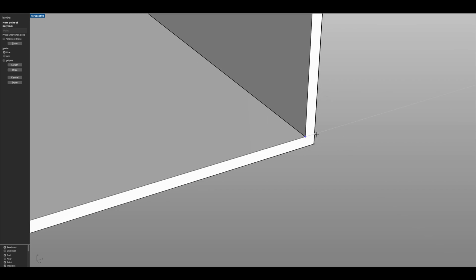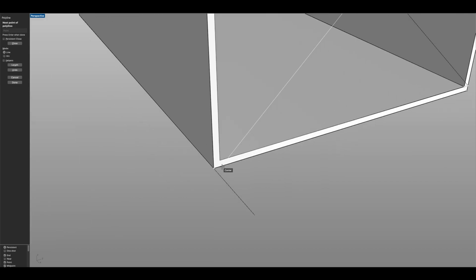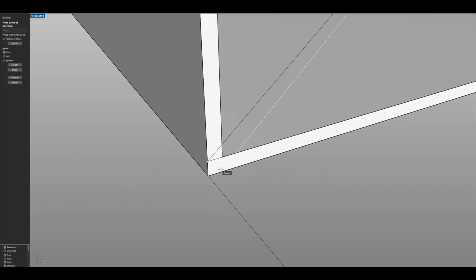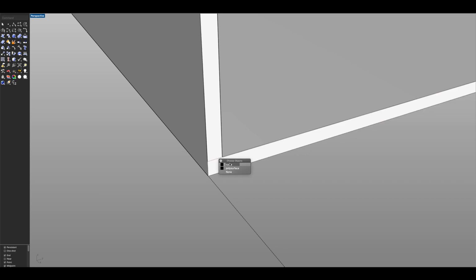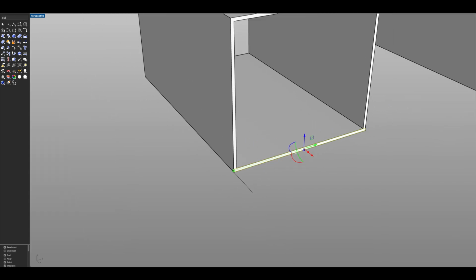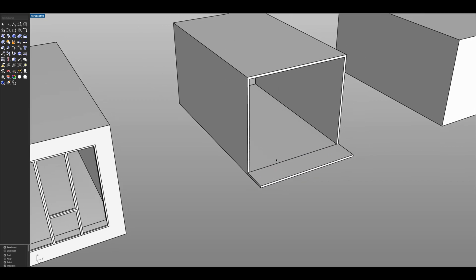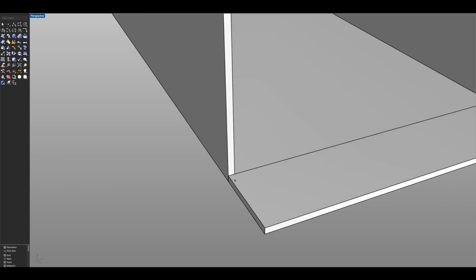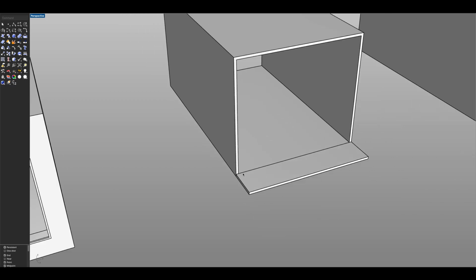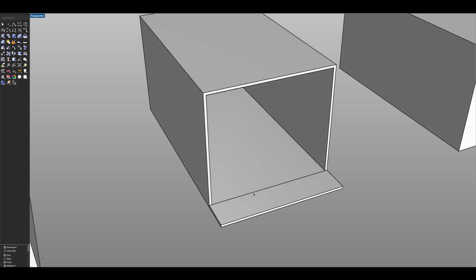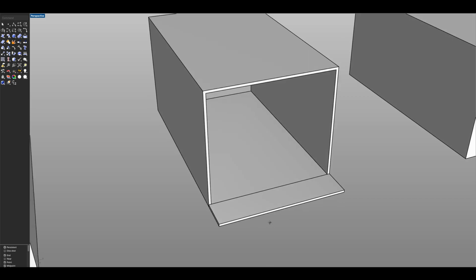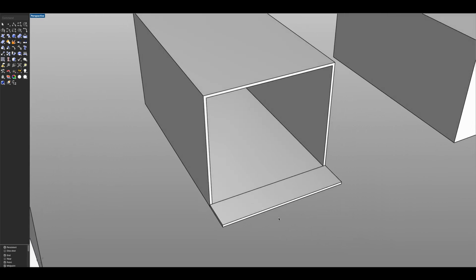As for the balcony, we're going to draw ourselves a new polyline like this. I'm going to bring it all the way out here, and then bring it back to where we started, and then close. And here I will now proceed to extrude this to the front, like so. Okay, now we can delete this curve. We can cap this. It's always important when building this model to make sure that different faces touch. This will be very important to get these all together in the next few minutes.